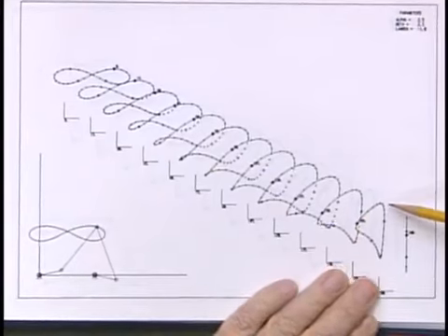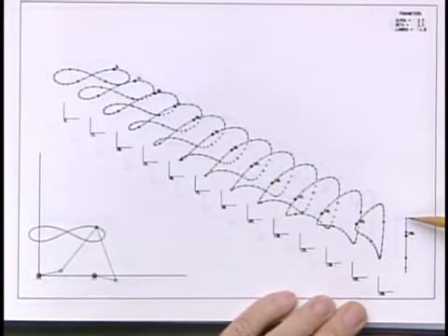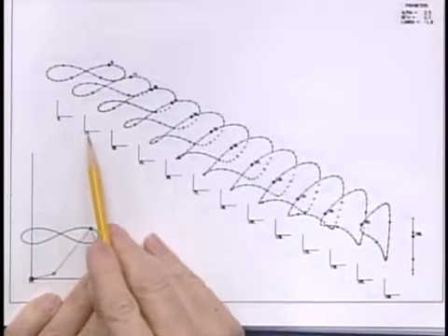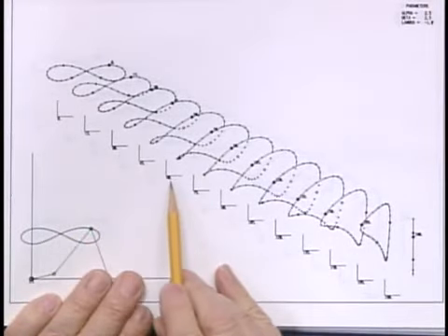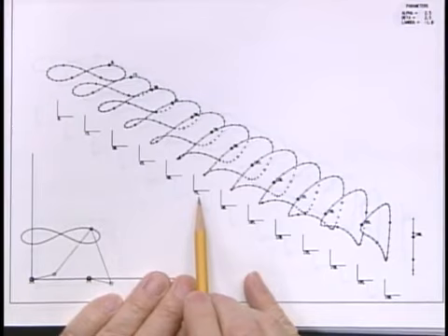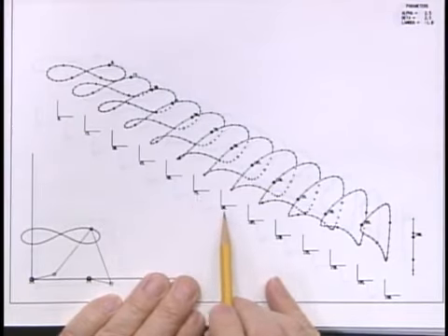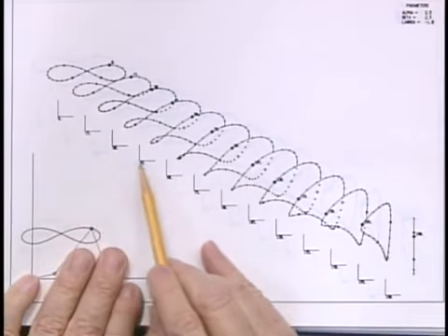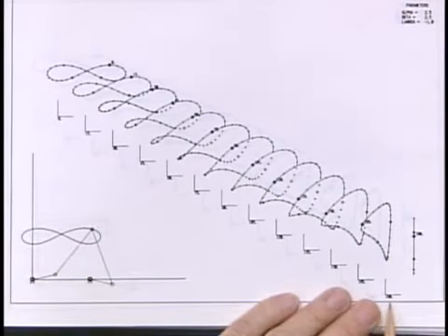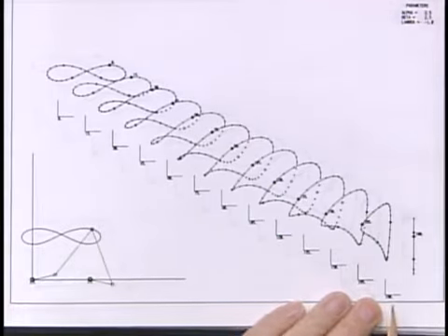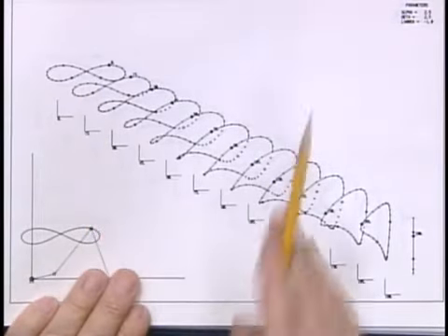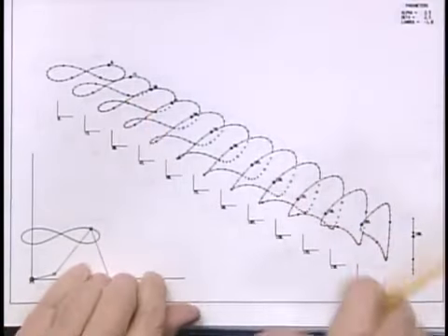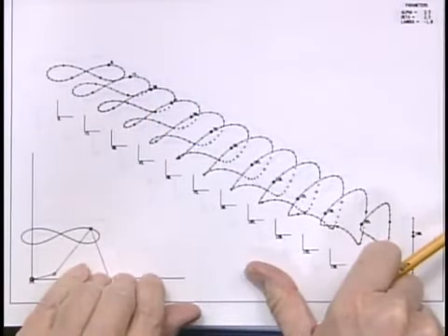Before I leave this page, let me point out that at a certain phase angle, these numbers down here represent the phase angles between the input and output gears, the gear on link 2 versus the gear on link 5. The numbers are not too readable at this scale. It's 0, 15 degrees, 30, 45, etc., through 180. So the only thing I have to change to go from this curve to this curve to this curve is to pull the gears apart, rotate one, and put them back together again, changing their phase angle.